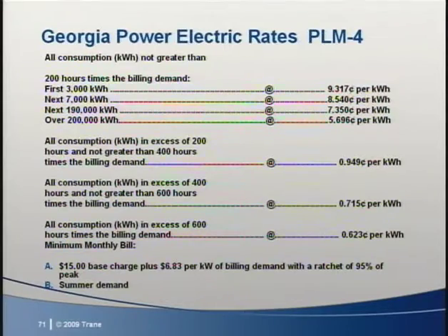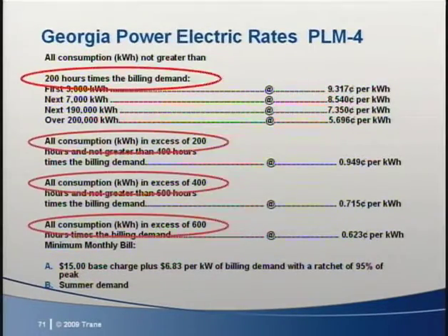There are 3 hidden gotchas in determining the bill that stick out. The energy charges change in steps. In utility rate terms, typical buildings have between 300 and 400 hours of kilowatt hour per peak kilowatt usage per month. Many buildings can never even reach the lower cost steps without improved load factor.